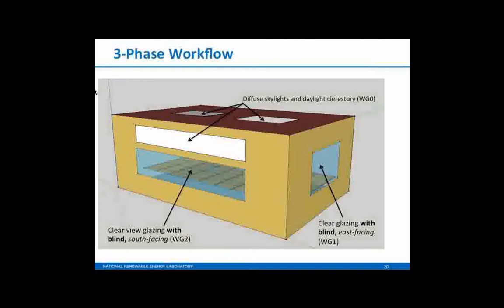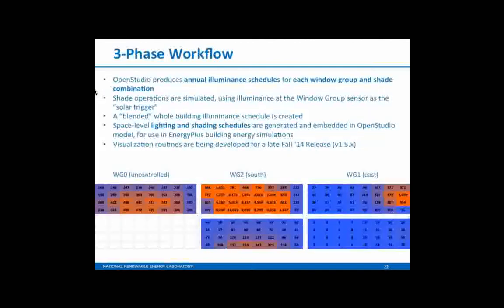So this is just the output from the simulation running, and it's already split the model geometry into these appropriate window groups, and it's simulating and creating the daylight matrices for the different things. And what you end up with is data, lots of it. This is a really crude attempt at just showing you that the model was sort of discretized into all the different apertures that are letting light in, and this is just a visualization of the daylight illuminance on the work plane in that space for 1 hour of the day. We've got all 8,760 of them. This is just one of them.